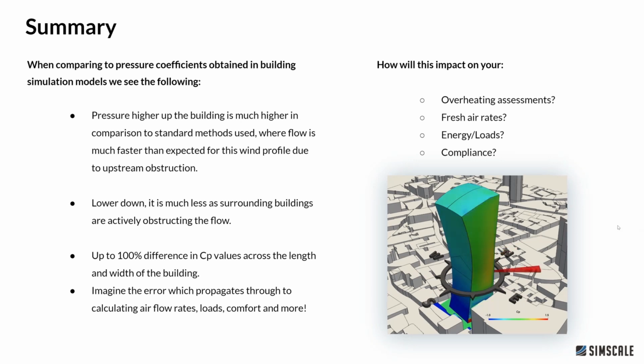It's very important. Again, my takeaway from this is a couple of key points. One is that we're not calculating wind pressure coefficients properly, and they're not being accounted for properly in our building simulation thermal models. The follow-on point logically from that is that there's a huge error when we calculate our fresh air rates, our ventilation, our thermal comfort, our heating and cooling loads, and hence energy. So one small value like the wind pressure coefficient will have a huge impact on your overall building design. Yep. Okay, Darren. Excellent, thank you.